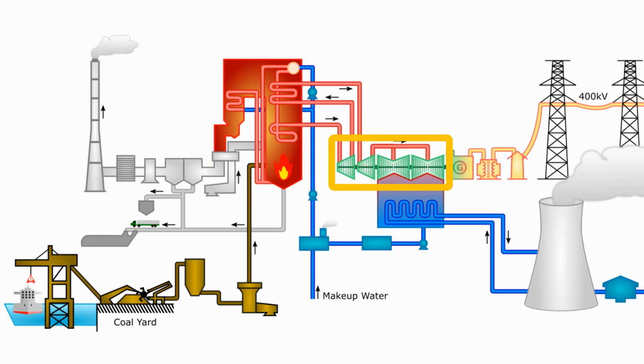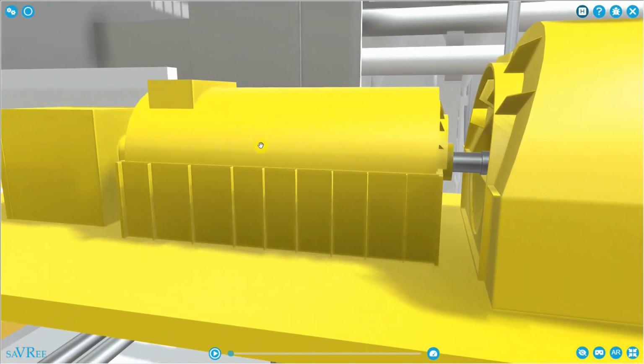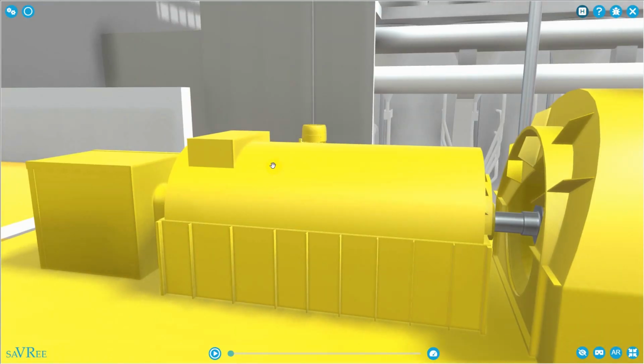We transfer that mechanical energy to our generator rotor, the rotor turns, and at that point we convert the mechanical energy from the generator rotor into electrical energy. And we have electrical power, or what we commonly refer to as electricity. A typical output voltage here would be around 10,500 volts. From our generator, maybe 20,000 volts. It really depends upon the design of the generator.